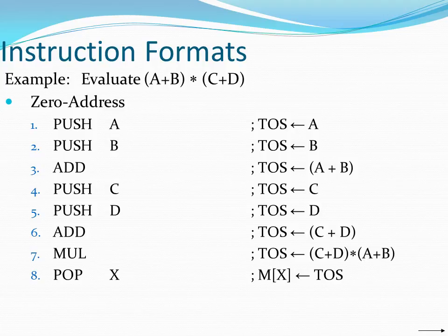There we indicated it with an arrow mark, but here we use an instruction: move LOC comma R0. In the instruction, the first operand is the source operand and the second operand is the destination operand. LOC is the source operand and R0 is the destination operand.